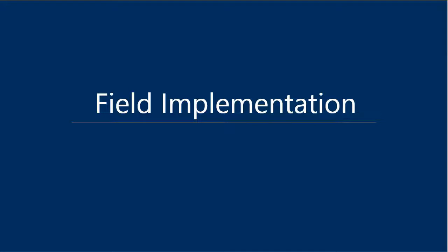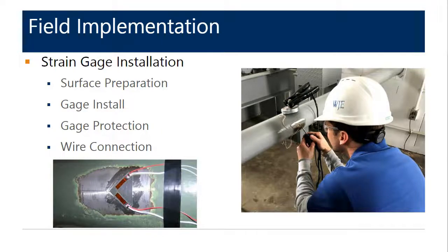Thank you, Adam. Now that we've established this fundamental method of measuring shaft torque using a strain gauge, we need to record that shaft torque during operation of the movable span and plot it against the bridge position in order to calculate the span imbalance. To accomplish this, we install strain gauges on the rotating shaft in the drivetrain as shown in the photos presented here.